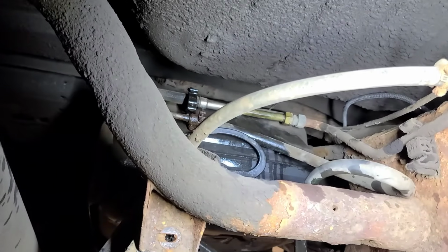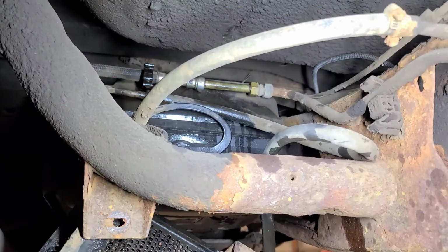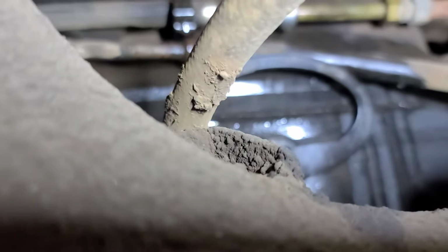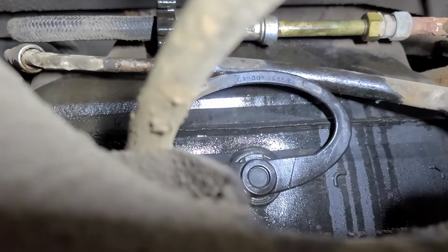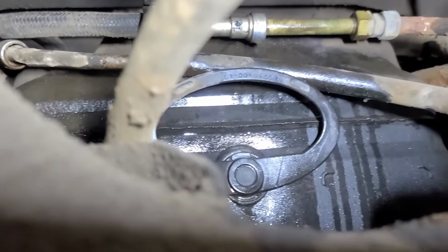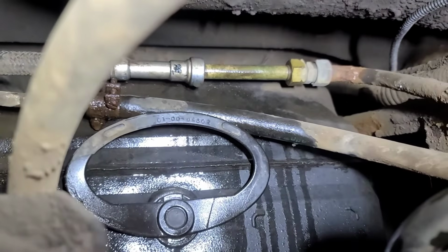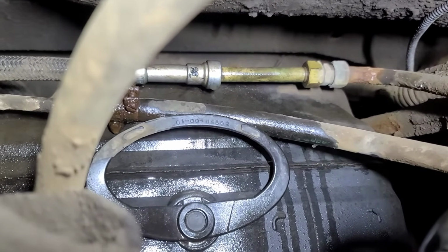So I did get that line off, and it must have been a repair fitting or something that somebody put on there. And if I put smoke pressure in the system now, you can hear the fuel bubbling inside the tank. But there's no leak here that I can see. I just pushed the line on partially. So I'm going to go to the hardware store and get some clear line and some 1/2-inch copper tubing so that I can make or reproduce this connection.